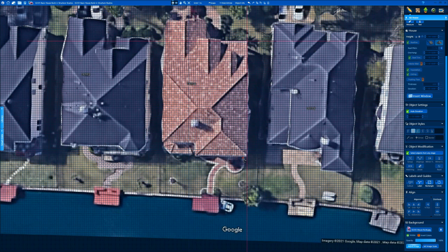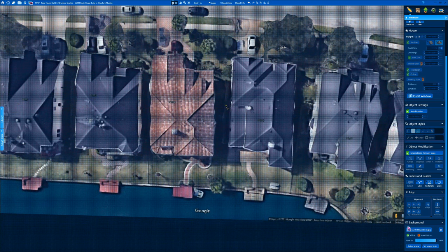So this is where we measured our 30. So we are going to get on the outside of the roof. Now watch out for the gutter. There's a 6-inch gutter, so be careful with that. When you scale, it's going to throw you off a foot. So we're going to go 30 feet, and that's what we're just going to say it is. So now there's our 30. So we can start tracing and drawing our outline.